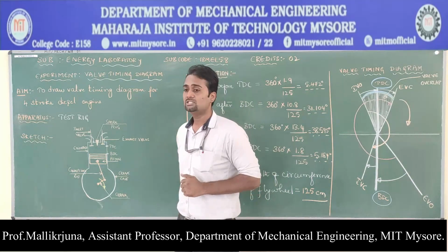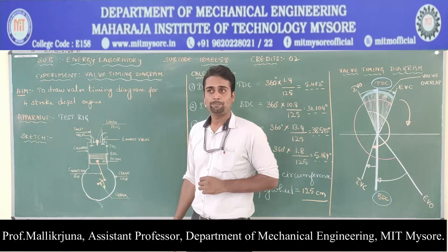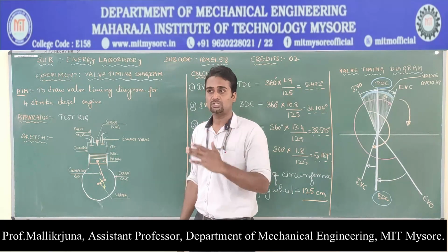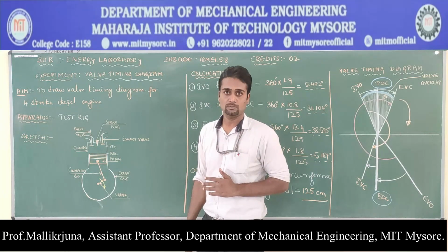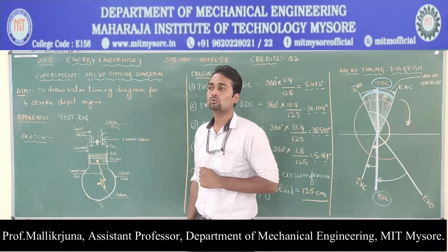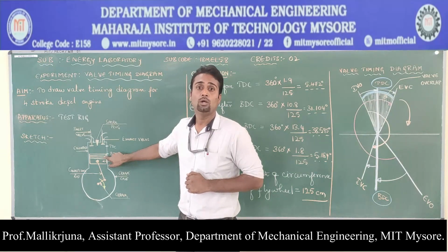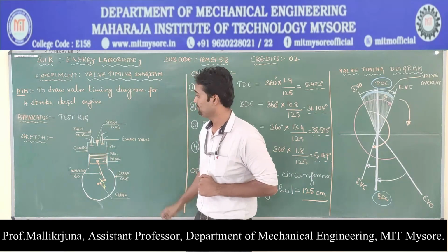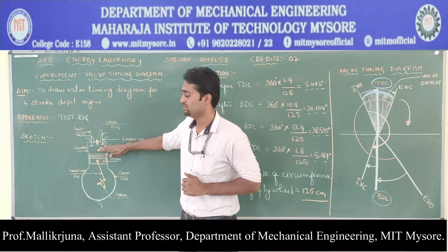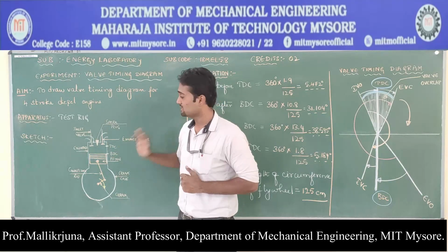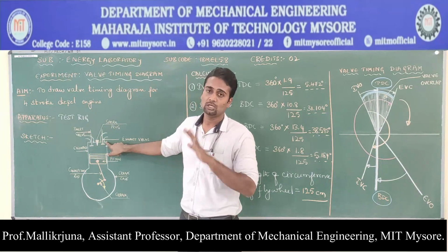In 4-stroke engines, we have 4 different strokes such as suction, compression, power, as well as exhaust. So during these 4 strokes, what is the position of the piston that we need to look onto? So now let us start with the operation. Very initial stage is suction stroke. During the suction stroke, inlet valve is open and exhaust valve is closed.